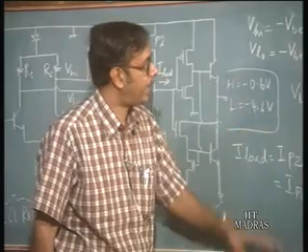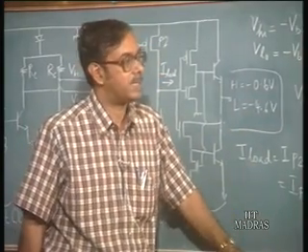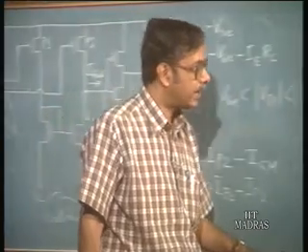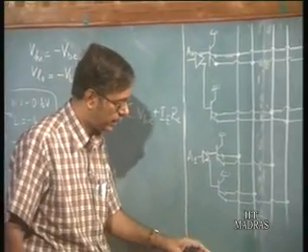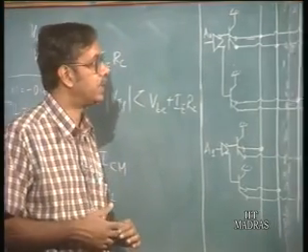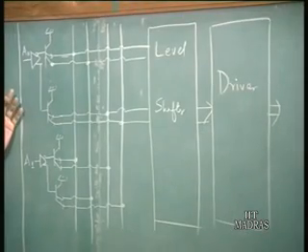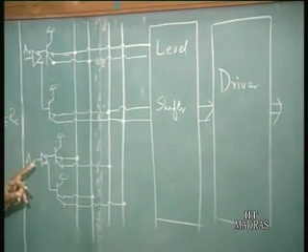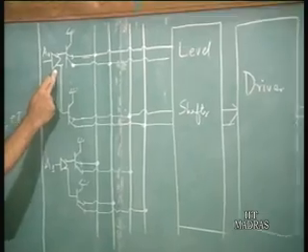So this is one way which people have employed in BiCMOS static RAMs. Another way I shall now talk about: another decoding mechanism uses a different concept. See here again the inputs are at ECL level. So what is done is first we have an ECL OR/NOR circuit.